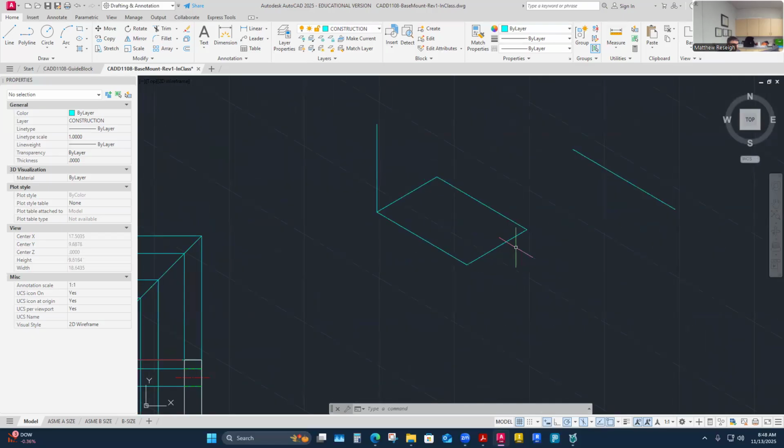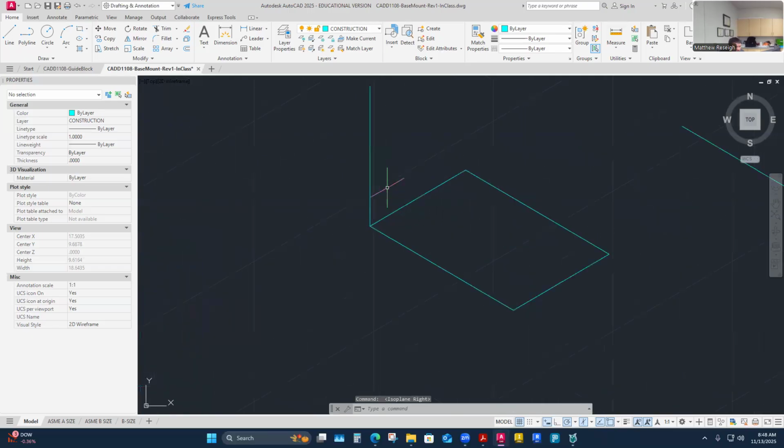That's what we want. And if I were to turn on the other, let me just show you, this one should be parallel to the right isoplane. I haven't changed it because to draw just lines, it doesn't matter which plane you're on, whichever one helps you view. But if I went to the isoplane right, these ones that project this way should be parallel to that one. And they are. They look like they're pretty good in alignment.